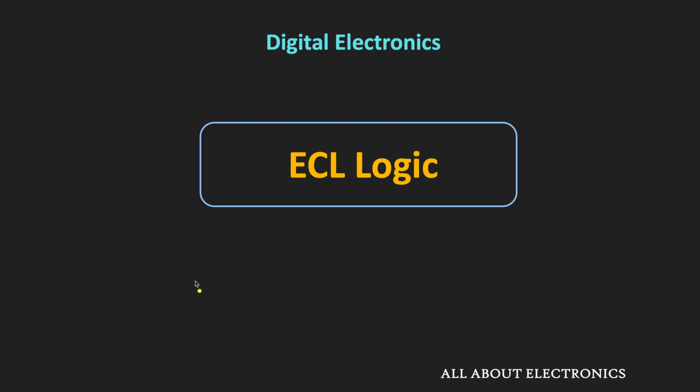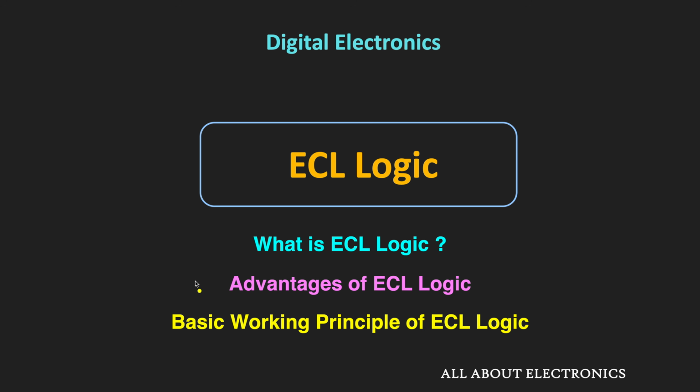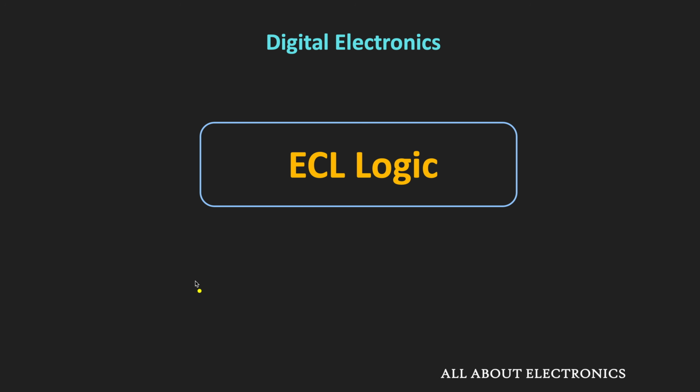So in this video, we will learn about the ECL logic. We will see what is ECL logic, the advantages of this ECL logic over the other logics, and the basic working principle of the ECL logic. And then after, we will also see the circuit of one of the popular 10K series of ECL gate like the OR and the NOR gate. And through that, we will understand the working of the ECL logic.